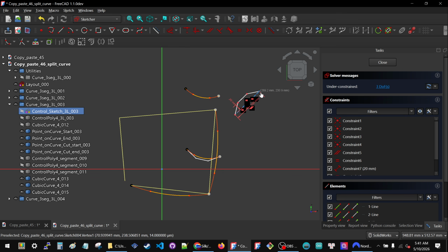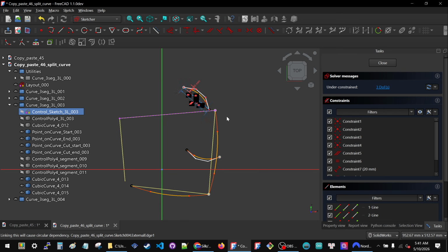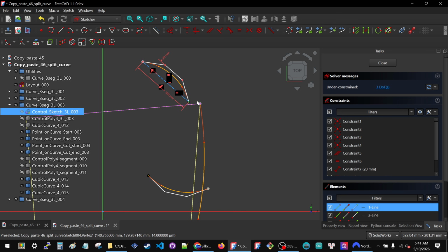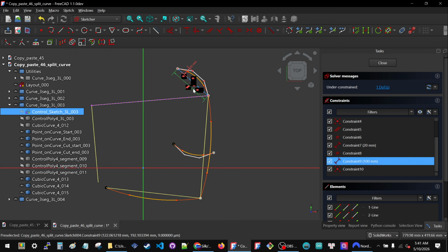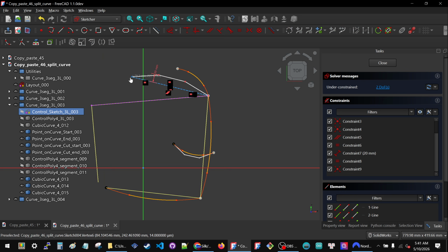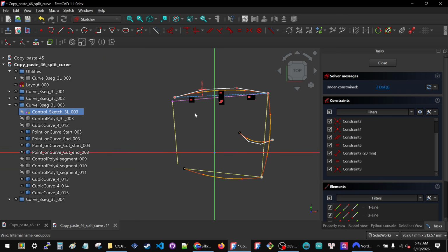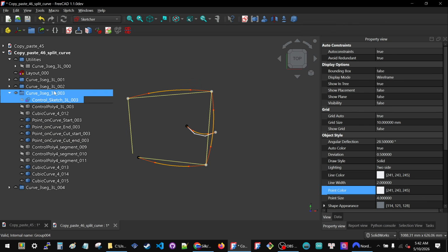So I'm going to turn this around, drag it a little bit, make my reference to the layout, take this point, the black one, and put it on here. Remember, I'm moving around counterclockwise. Hit the C key, delete this dimension, drag this out and put it close to where we want to go. Select 2 points, hit the C key, and hide the sketch.